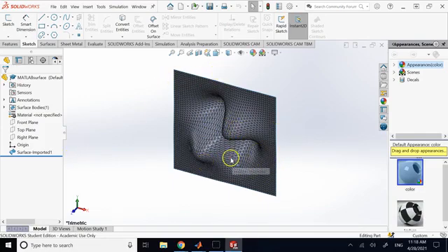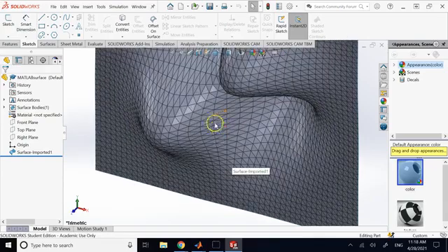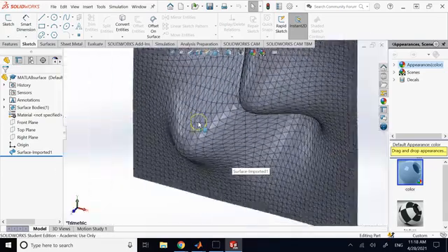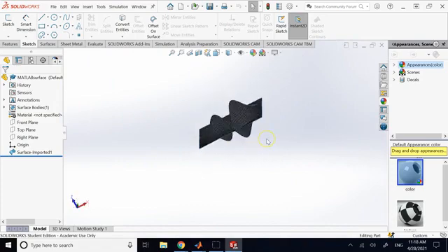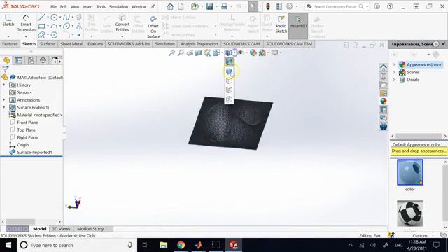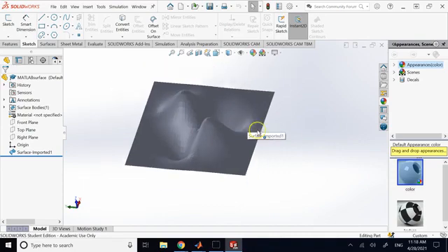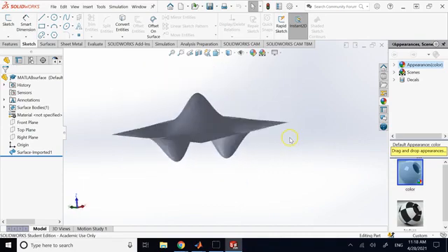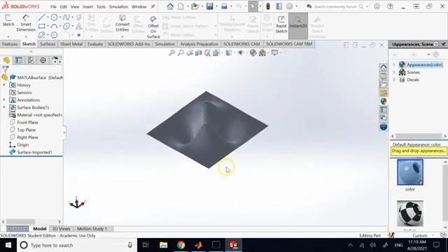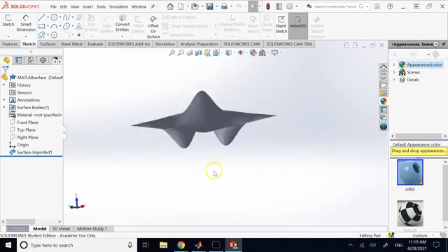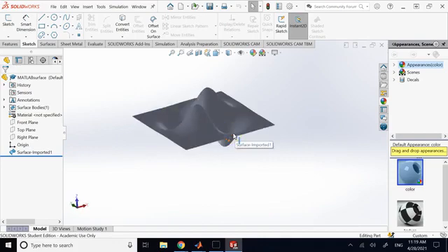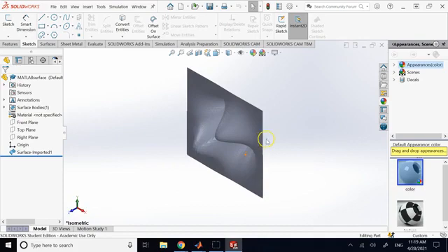So you clearly see all of the triangles that I mentioned, correct? So you see clearly the tessellation has been done using that STLWrite file. And if you want, you can remove the edges to see the surface a little bit better. Okay, so the surface is generated, and now all I need is to create a cube, a block, using this as its top surface, and then convert that now into an STL file ready for 3D printing.